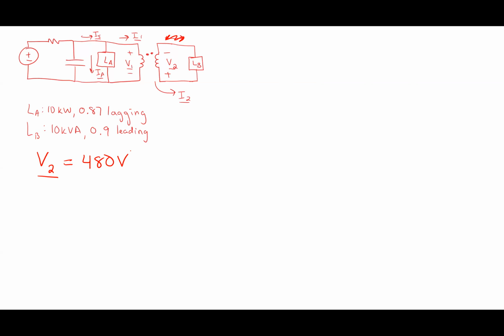Well, could I use Ohm's law? All right, let's go with that suggestion. I could if I knew the impedance on that load, which I could figure out. But I'm going to say the simplest way typically is to say S is equal to V I conjugate.